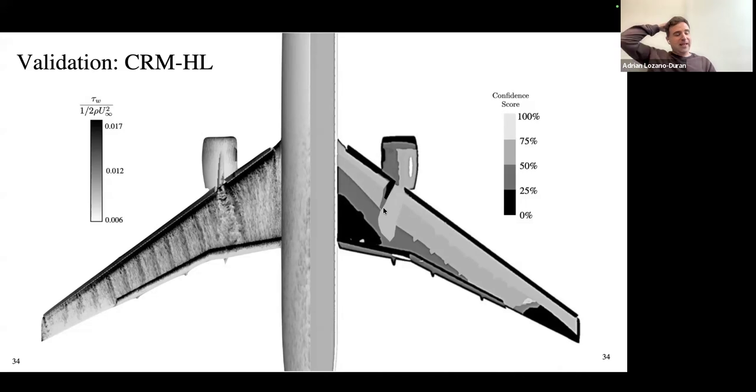Our guess here was that the separation that our model learns about from the training data doesn't follow the same physics as the separation that we have here. So our conclusion from this is that the model wasn't able to capture this physics, and because of this, at the wingtip and the roots, those forces are not the correct ones, and that's affecting the pitching moment.